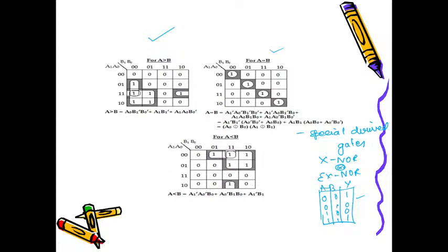So even when you simplify and see, you will get the same thing. And also you know the logical expression of XNOR. What is the XNOR logical expression? Y is equal to A bar B bar plus AB. Which signals contribute to high output? It produces the output high when A is 0 and B is 0.